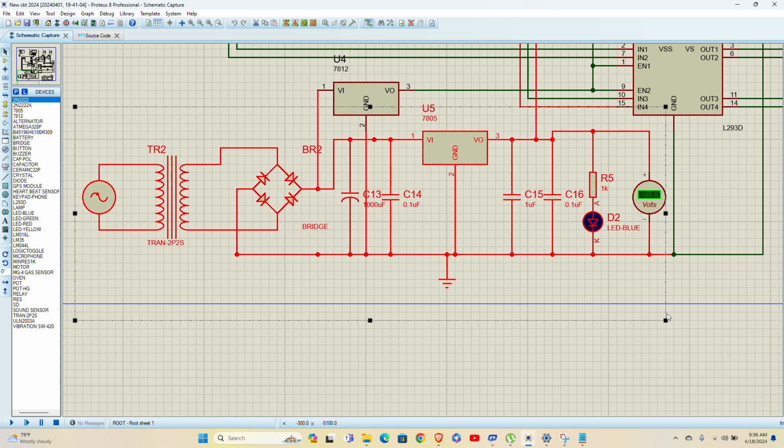Power supply consists of AC input from Tanesco. Then here is a transformer which steps down the voltage from 240 to 12V, but it will remain AC because it's not filtered. So after here we'll put a bridge rectifier. This bridge rectifier negates all the negative voltage which comes from this one.